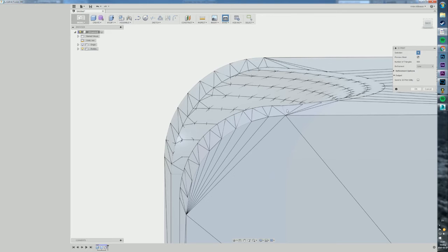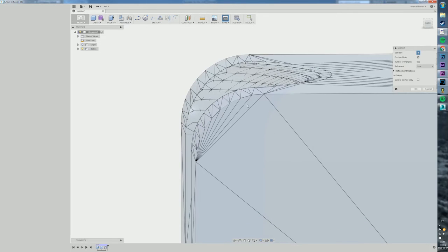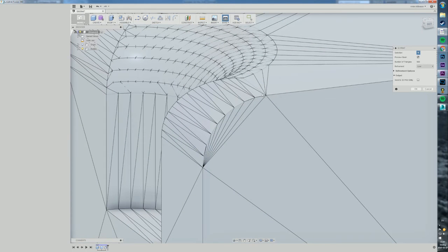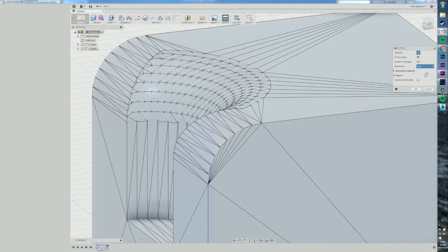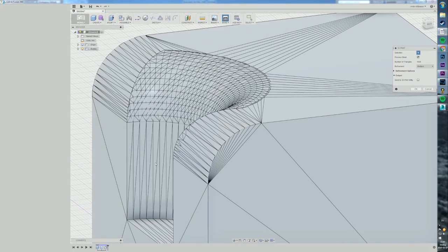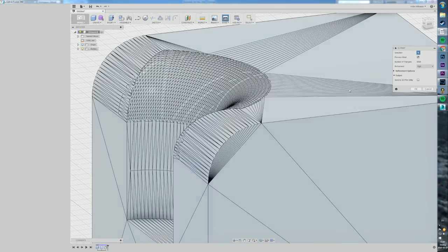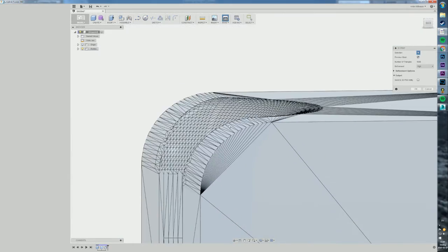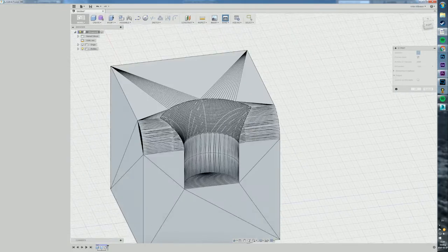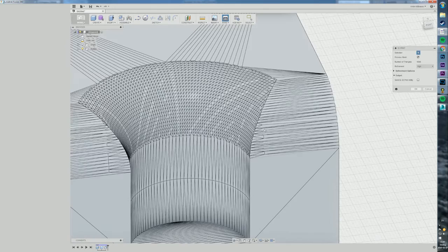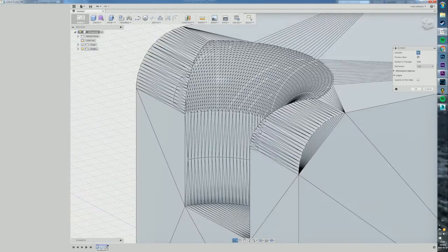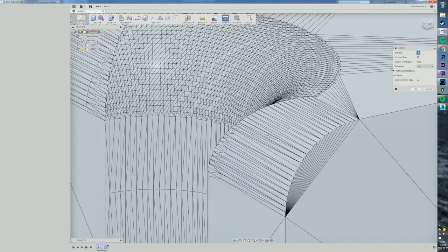So if you look at a 3D print, you see the layers. This is almost the same thing. So you define a curvature by having multiple steps. You can, of course, increase this. So you can go to medium and decrease the amount of triangles, or to high where you have a lot of triangles. So usually this high setting is good enough, but for some printers, let's say a Formlabs or SLA printer, where you have incredible detail, you sometimes need to